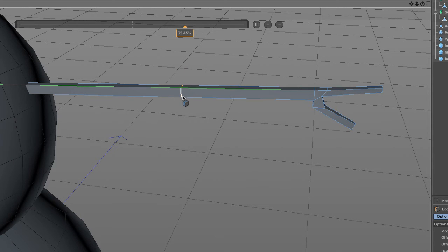Okay, so it's amber, it's selected. There's a slider up here, and it's reading out as 73.45%, whatever the heck that means. What C4D is doing is measuring the distance between two edges on the object. So it's the distance from this edge and the distance from the edge buried within the snowman. It's saying it's 73% in the positive direction. So if I slide that slider, as sliders are meant to be slid, it moves the loop back and forth. Okay, I want the loop right about yonder.